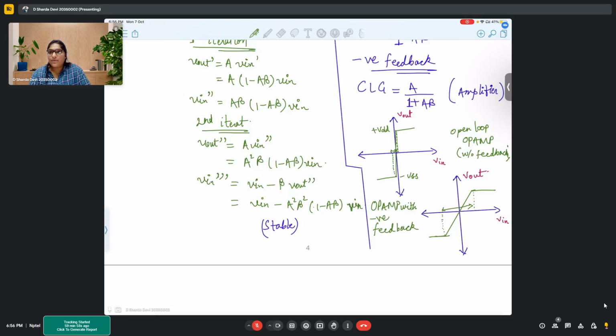It picks up some noise, some thermal noise, which is very, very small. Then the oscillator starts increasing that noise until it reaches a certain level, and that is basically the steady state. In the steady state, you will get some output out of your oscillator, and that is possible only because of the positive feedback.